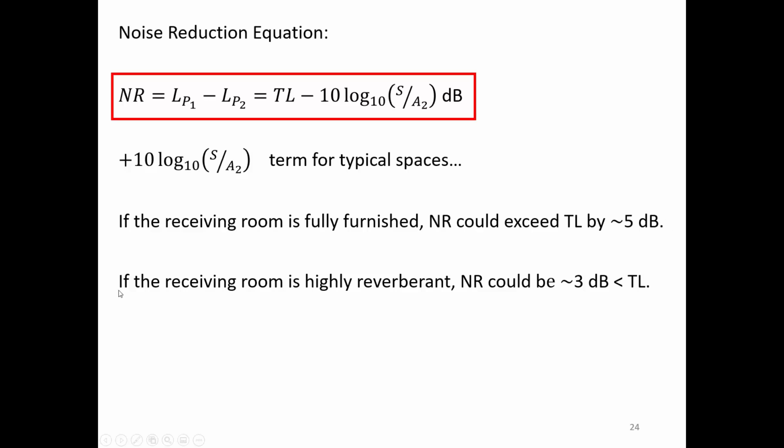But if the receiving room is highly reverberant, your noise reduction could be roughly 3 decibels less than the transmission loss. So it just kind of gives you some rules of thumb you could go by.